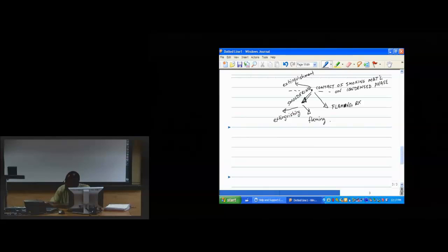We put this ignition source close to it, and because of the mixing of the pyrolysis gases with the adjoining oxidizer, there's a flame, a premix flame initially, that sits above it, this initial flash of a premix flame that consumes this initial amount of fuel that had been liberated in the pyrolysis process.